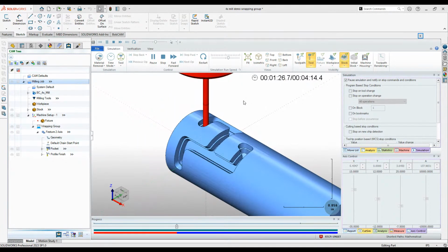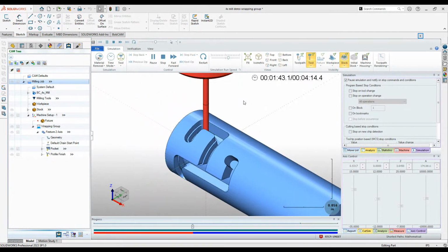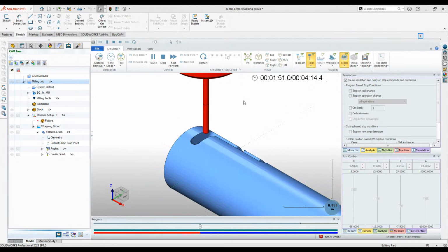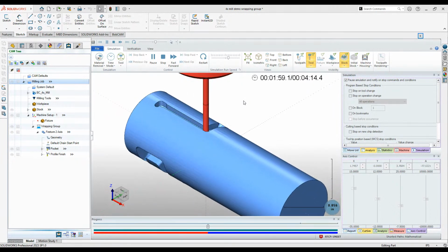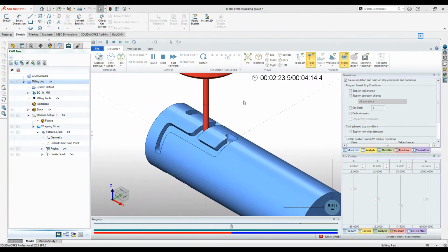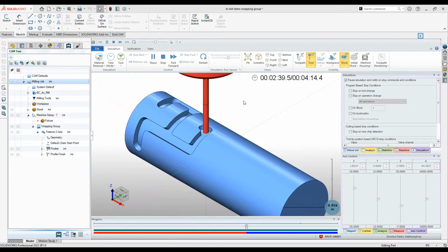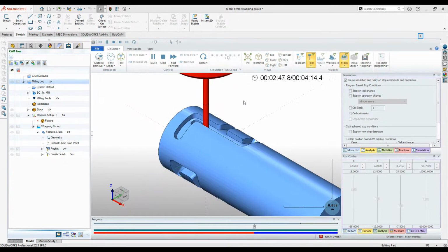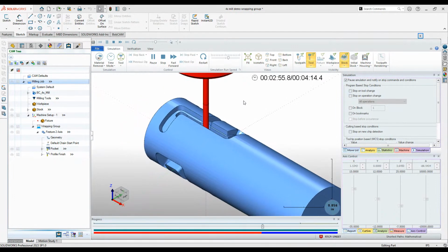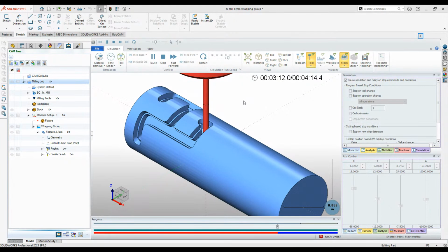Doing the second depth of cut with this pocket, and then going to the next pocket to pocket it out, and then a profile finish around the two pockets after. So essentially you can see the tool is just going down in Z, and then it's moving back and forth in X while the part is being rotated around the A axis rotation to give us this pocket operation.